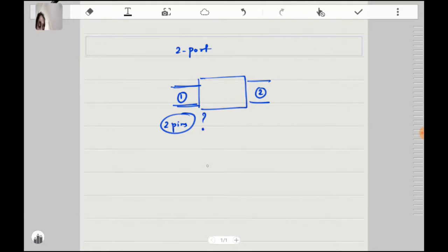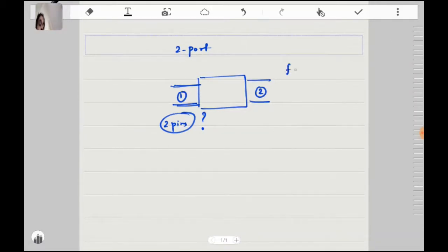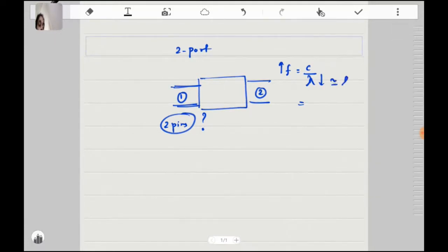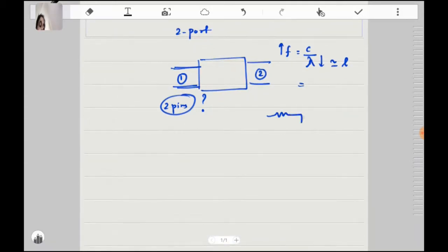This is the reason we come to high frequency, because when you say high frequency circuits or devices or transmission lines, as we have seen earlier, high frequency is nothing but c by lambda. When you go to higher and higher frequency, the operating wavelength of the signal becomes smaller and smaller. It is comparable to the physical length of the line. So the voltage changes instantaneously, and if the impedance is not matched, the wave we have seen in the transmission line will have a distributed component,